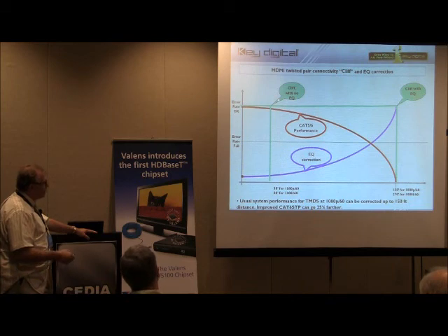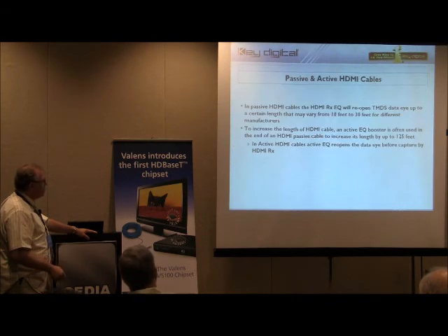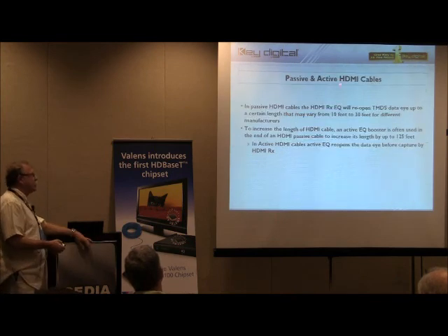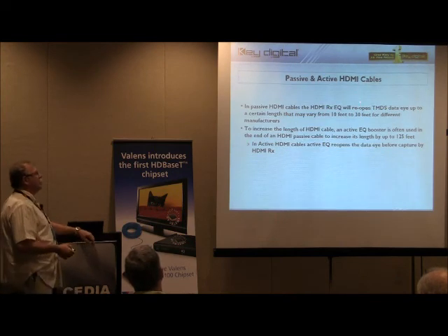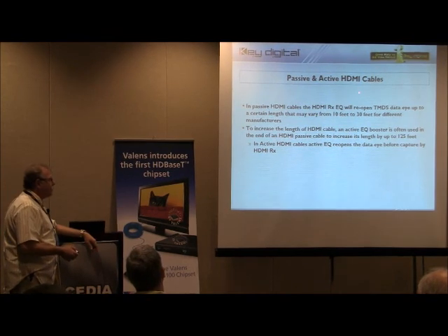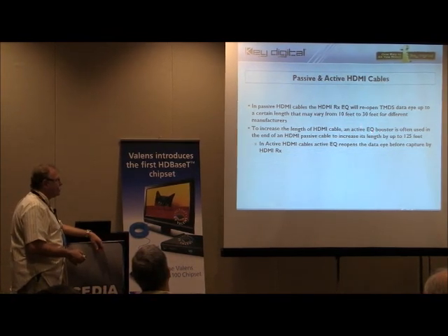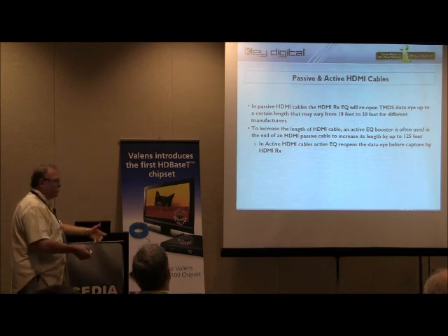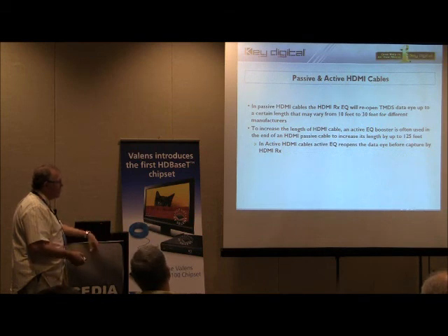Now, there are a few different EQ systems. Actually, I'd like to say a few words: to extend HDMI cable capability, some people use EQ boosters on the end of the HDMI cable that effectively do the same thing. They reopen the eye, they equalize the cable, and they can make the length of the data go up to probably 125 feet.